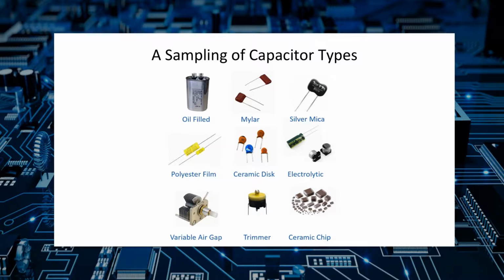Capacitors are used in all types of circuits. In power supplies, for example, capacitors are used to smooth out AC and to filter out ripple. In audio circuits, capacitors are used both to block DC current, called blocking capacitors, and those are normally used between various stages of an audio amplifier, as well as to filter out noise or to allow the actual audio portion of the signal to bypass certain components, and those are called bypass capacitors. In other circuits, the capacitor's ability to charge and discharge at specific rates is used to generate timing signals, like a clock or a one-time pulse.